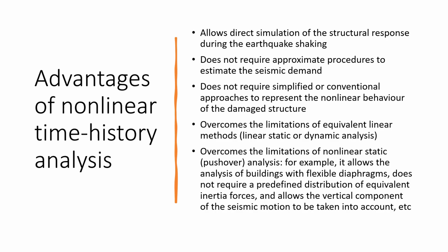Advantages of nonlinear time history analysis are obvious. This method allows for the direct simulation of the structural response during the earthquake shaking. It does not require approximate procedures to estimate the seismic demand. You directly compute it. It does not require simplified or conventional approaches to represent the nonlinear behavior of the damaged structure. We are representing it, we are modeling it.